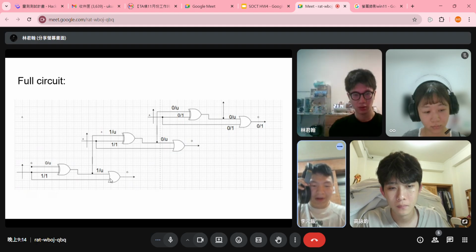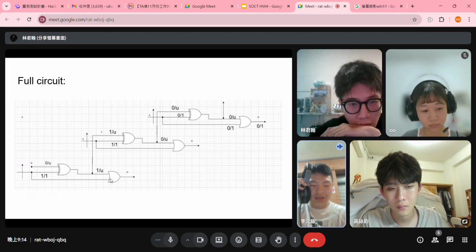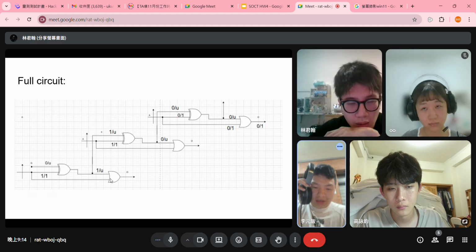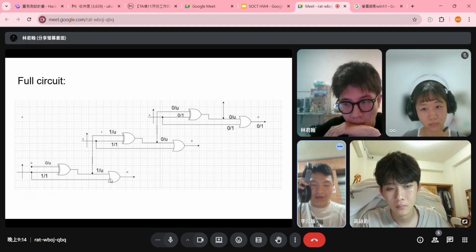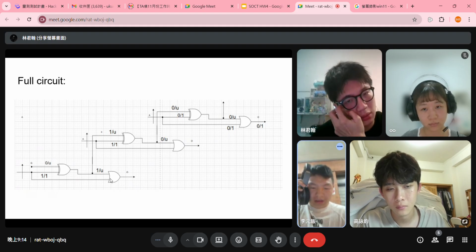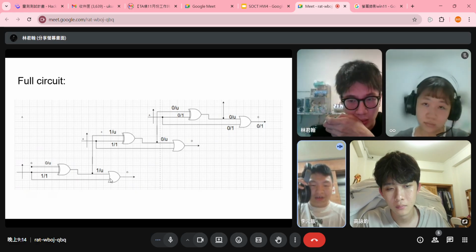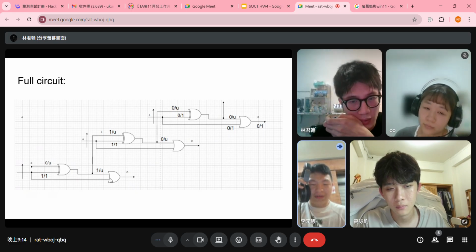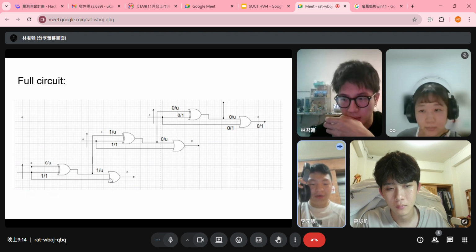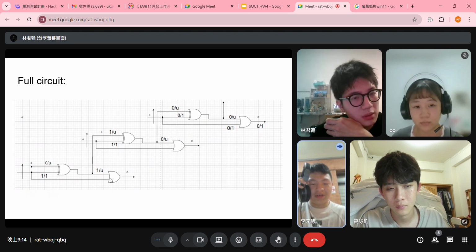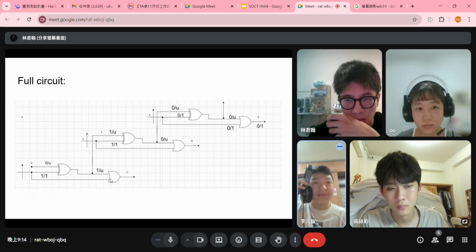This is the priority dependency, which is crucial to test generation, and it is caused by the exclusive OR, which is a priority gate. Since this may happen whenever an exclusive OR gate is in the circuit, the more complex the circuit is, the more time frames we need to obtain the required input for our test generation.